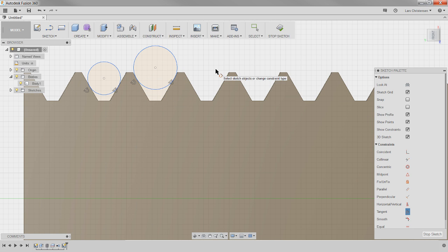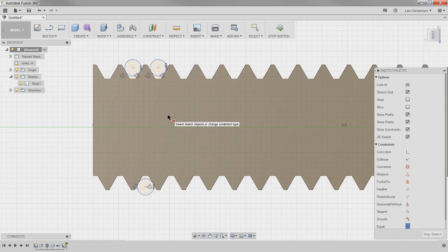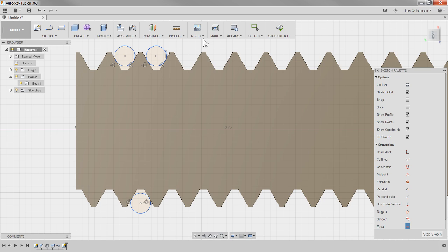And then you're actually using the same size wires for all 3. So we can make these equals. And by the way, when you buy a thread wire gauge set, it comes in sets of 3. So what you do is you're now putting your micrometers and measuring up on top of these 2 wires, and then this one down here, for people who don't know this. So we are now tangent to the thread, and that's kind of how we determine this.